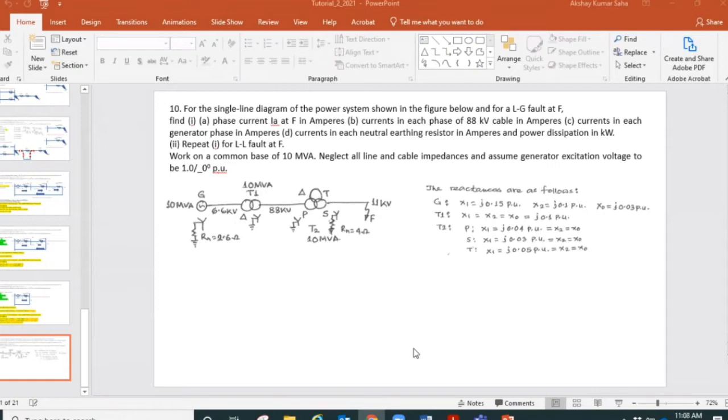So if we analyze that one, what will we get there? We'll get multiples of that fundamental frequency present in the waveform that we are getting from the generator output. That causes the harmonics. All those multiples are harmonics. The fundamental is considered as multiple of 1. So 50 times 1, that's the fundamental.